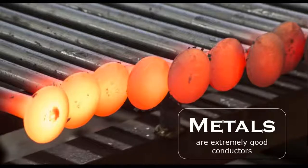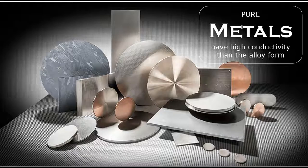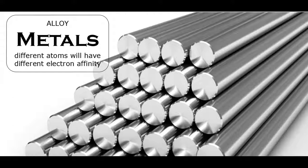Now, let us go first to metals. In metals, we have three things to remember. Firstly, metals are extremely good conductors of heat because relatively large numbers of free electrons exist that participate in thermal conduction. Second thing to remember is that the purest form of metal will have the highest conductivity than the alloy form. And last thing that we have to remember about metals is that in the alloy, different atoms will have different electron affinity. Thus, the movement of excited electrons becomes hard.